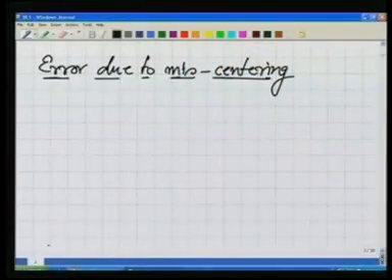Now this is a slightly difficult exercise, difficult in the sense that a lot of trial and error is involved, and we can never reach the true orientation, perfect centering. So what to do in that case? We should know, if at all we are introducing some error due to miscentering, what kinds of errors will be propagated into the angle that we measure. So this is what we are going to see now. We are going to see error in angle measurement due to miscentering.